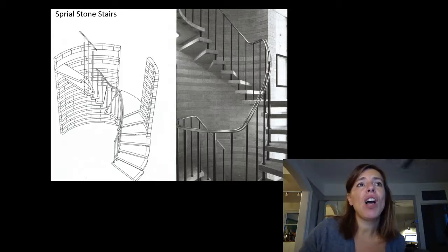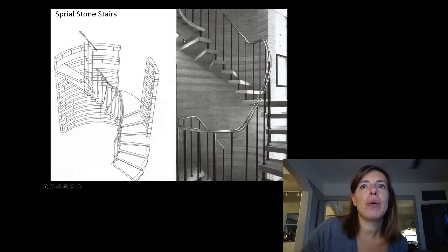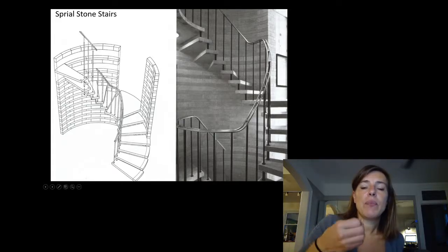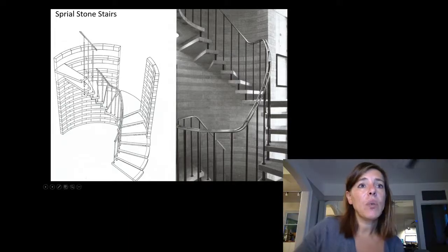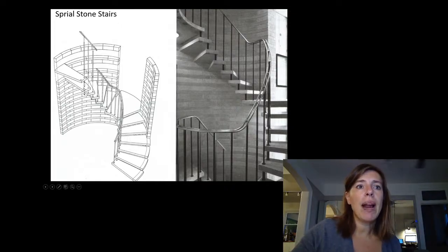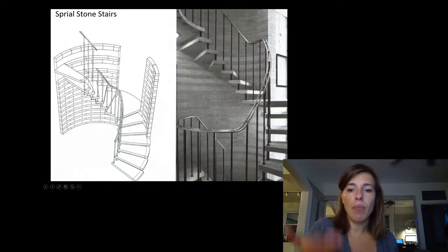This one's cool. Dave talked about the stair application of this, but what I really like is how they built these guards. So they had a hole drilled through. This is the base plate, the base cap, and then this was a rod that's bigger that can pass through. This is what's stopping the 2 stone elements from crushing on each other. So these were bearing in between the 2 stone steps, and then this rod dropped down through the assembly to the bottom cap.